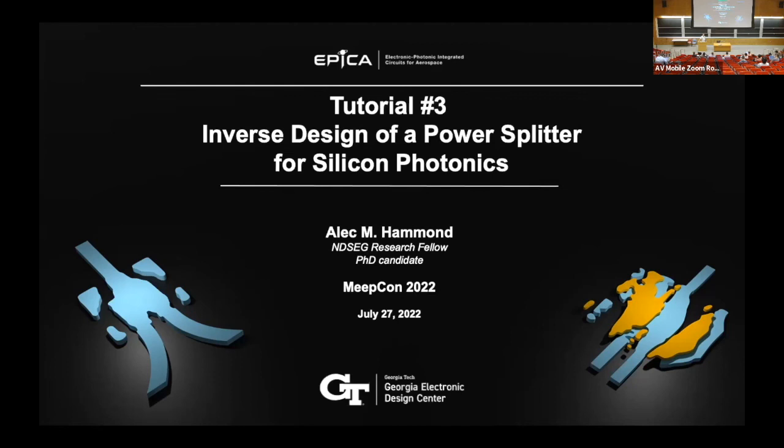But we did some cool work recently where first of all, we had to invent a bunch of optimization constraints that could account for rules that were previously ignored in a lot of other previous works, but were actually more significant with respect to the fab compared to things like minimum length scale constraints. And the things I'm talking about are like minimum area and minimum enclosed area.